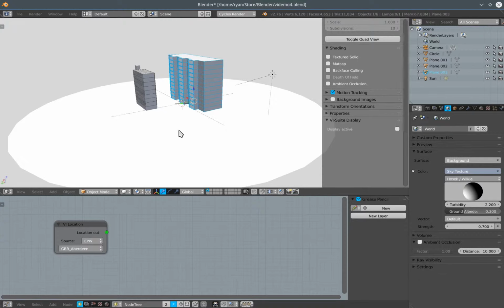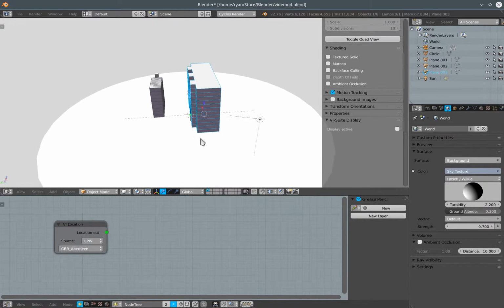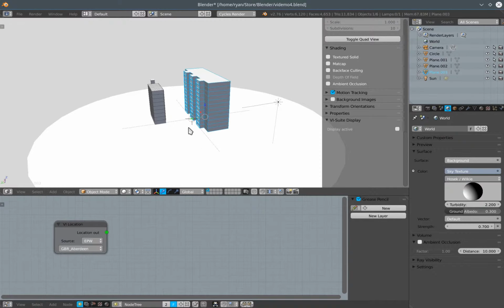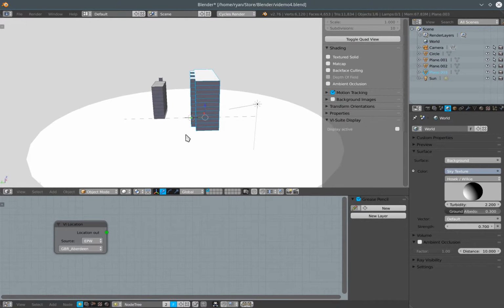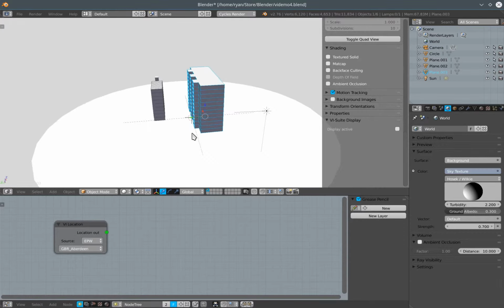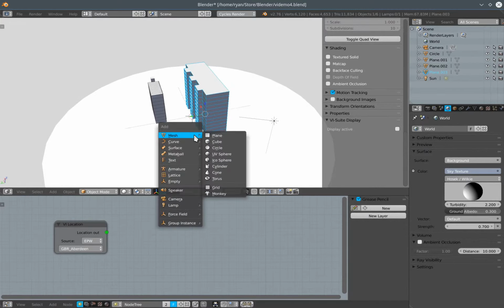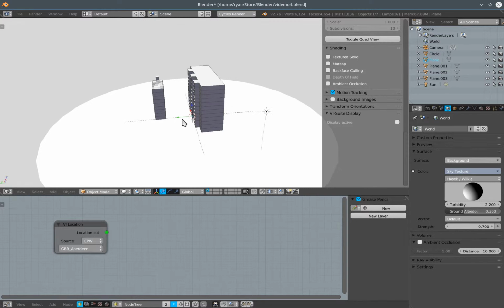So the basics of a shadow study analysis is firstly to have some geometry, which will either be shadowed or will cause shadows, and to define within the scene where we're going to calculate or define the location of the points for which we're going to calculate how often they're in the sunshine and how often they're in shadow. So for the shadow study analysis we can create specifically some geometry.